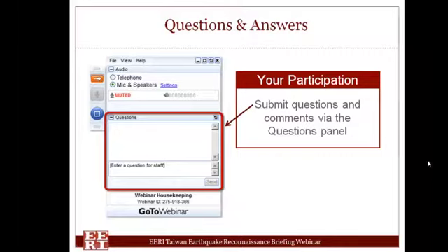This is Joseph. I'll try to answer that question. The answer is no, because at the time of our visit, there was no sampling being done. And I'm pretty sure in the following months, there will be geotechnical investigation for the liquefiable sites. So hopefully at that time, they will be able to identify the critical void ratios. But at the time of our visit, we didn't have that time to make that assessment. The only information we got is that one of the slides I've shown, that the repeated liquefaction sites have an SPT blow count varying between 2 and 5.